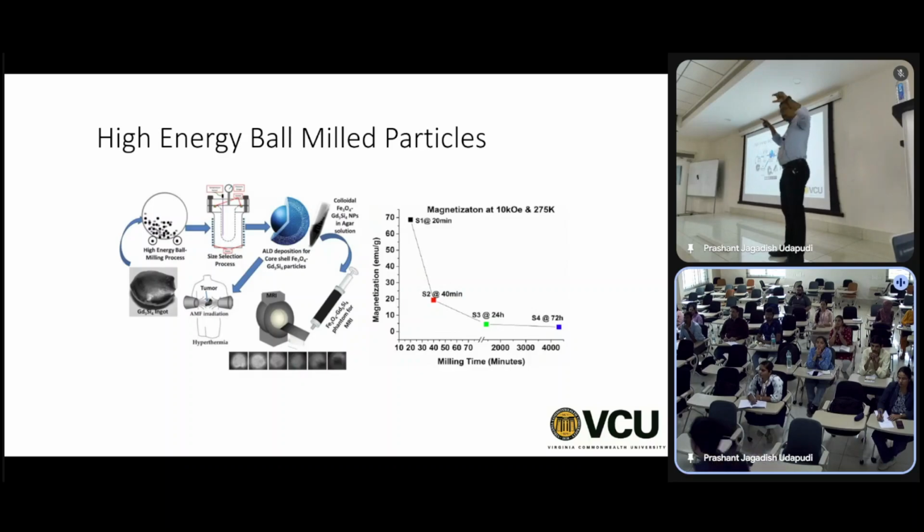If you look in the scanning electron microscope, you'll see some small residual phases of 5,3 or 1,1 gadolinium silicon, or gadolinium 5 silicon 3, residual phases in the material, right? So you have to maintain the right stoichiometry. Once you have this ingot, you do thermal treatment to get the monoclinic phase, okay?